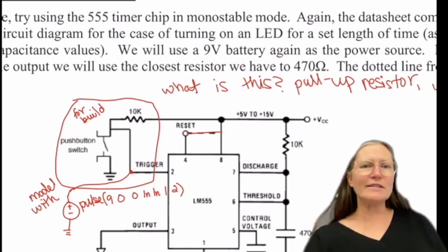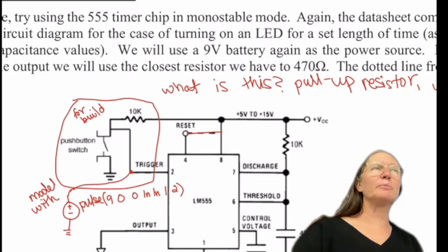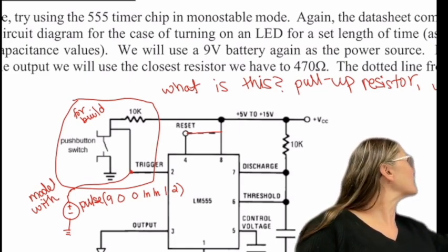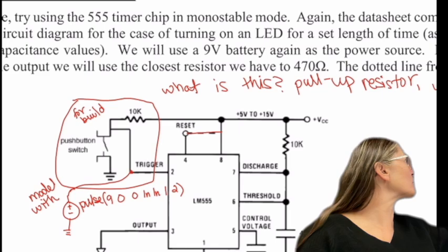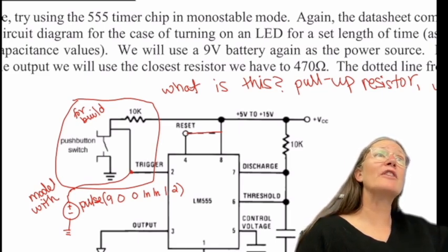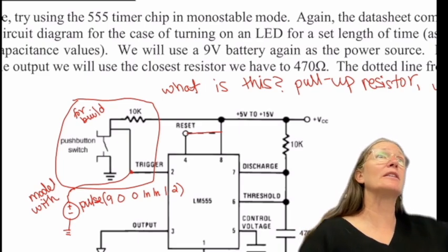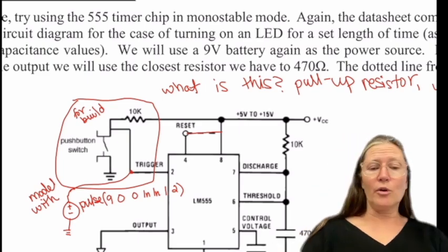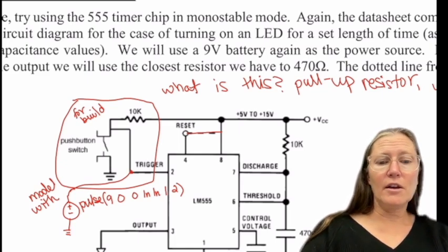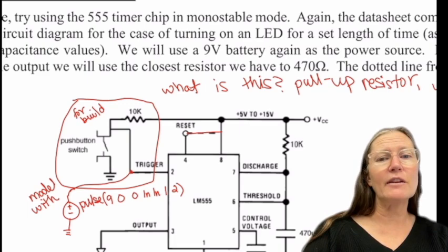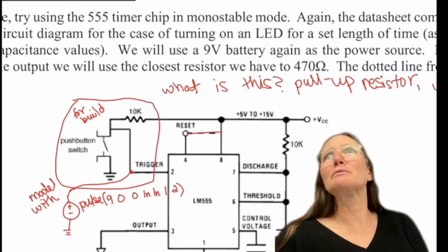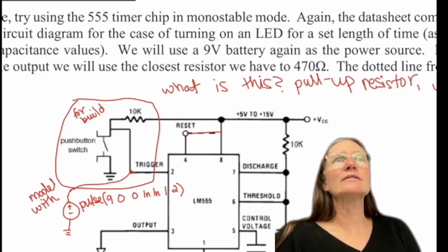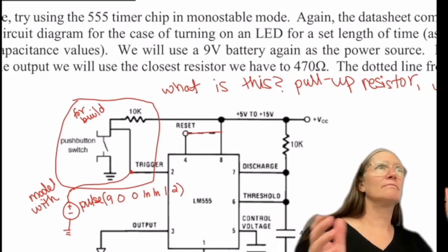A couple people were asking me about how to put in this pulse directive. It is where you normally have the voltage. You can just click on where you would normally put in your DC voltage value and type that command in there instead. Instead of, a lot of times, 5 volts, you're just going to replace it with that whole command of pulse. And you can do sinusoids the same way. You can put sine and then that function.